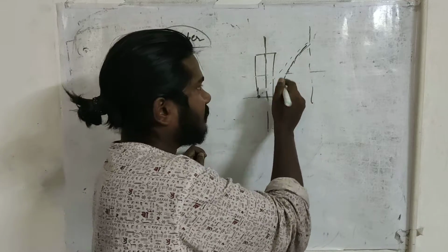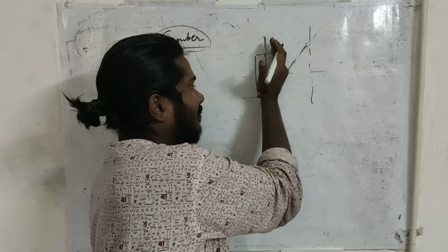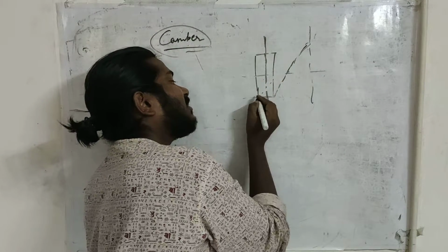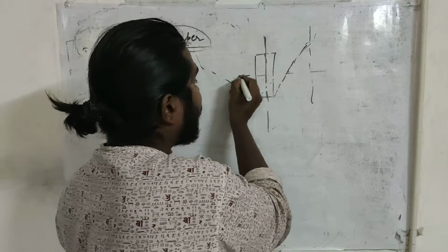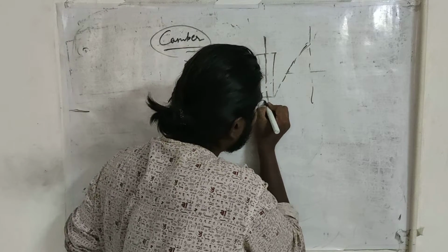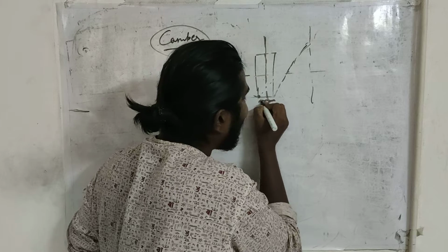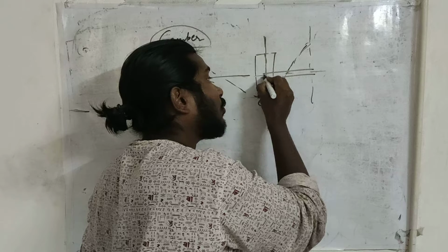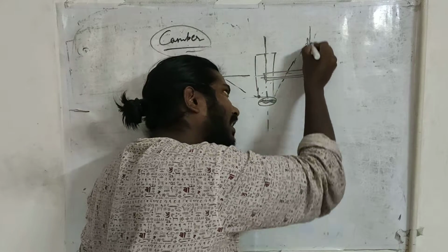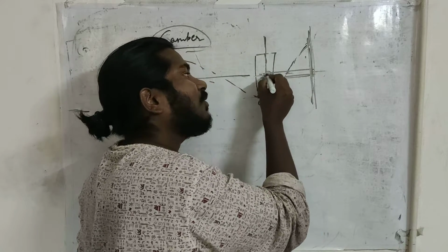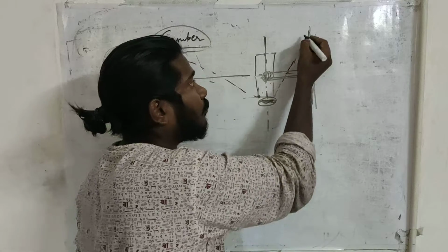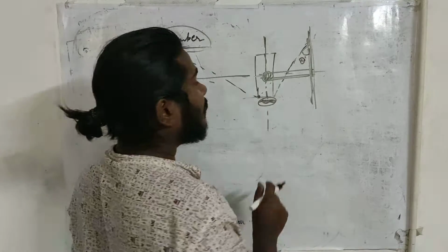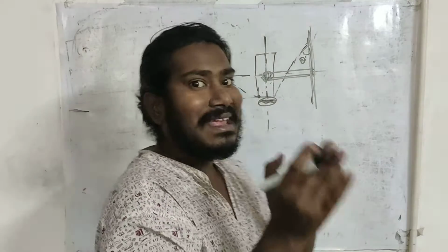Take it here, not there, right? Aligned at this from here. From here it will happen, or maybe in this direction it will happen. Whatever the case, your tire width decides the maximum camber angle, as well as the distance of the tire center contact patch from the inboard hinge point. These two factors will decide what is going to be the angle of camber. What could be the minimum and maximum value of camber angle?